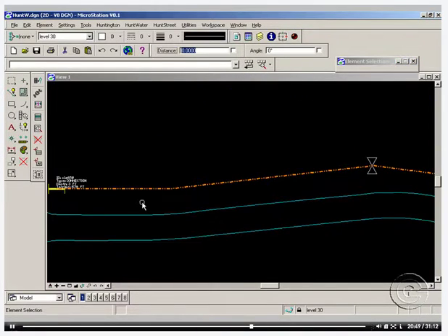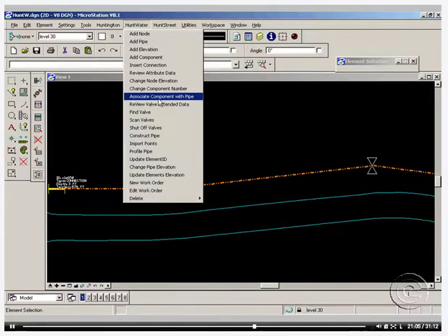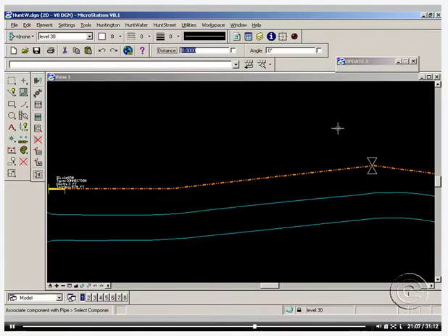The same way we go in and use a line to construct basically this pipe, we could have also had in our map some either valve or component item that have no attributes, and then use those to associate them with the pipe that we already drew, and then have it linked to the database. Here we can just go to the menu system and hit associate component with pipe, and go in and tag the component that we want to associate with the pipe, accept it.